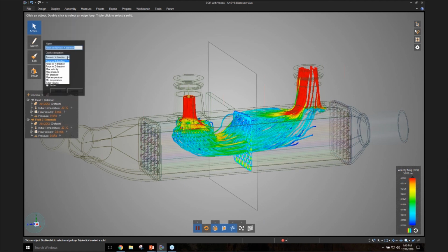You can see force in different directions and so on. I want to point out that the goal of those calculators is to help provide quantitative directional guidance. You remember when I had the splitter with the duct and I was trying to get even flow between the top and the bottom? The purpose of the calculator is to get a numerical value which shows me that the flow is balancing out. Of course, I can also look at it visually like I'm doing here.